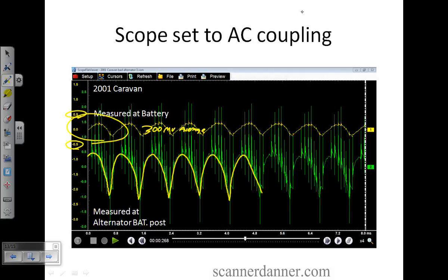Okay, so I know what you're thinking at this point, and that is, well, how did you know to go here? Here's the symptoms of this vehicle. It was at a transmission shop. No, it wasn't. It was at a shop that thought this had a transmission problem. The issue with the vehicle is it had a vehicle speed sensor code in memory.